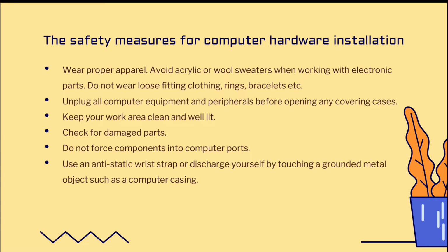Third, keep your work area clean and well-lit. Fourth is check for damaged parts. Fifth, do not force components into computer ports. Sixth, use an anti-static strap or discharge yourself by touching a grounded metal object such as a computer casing.